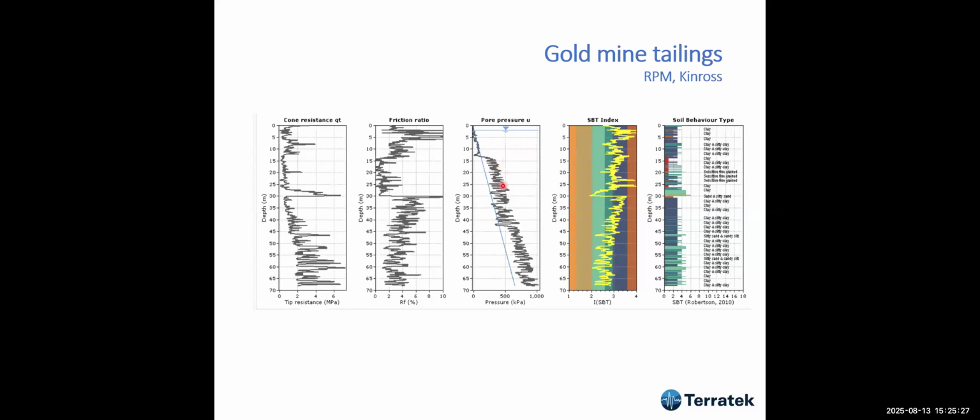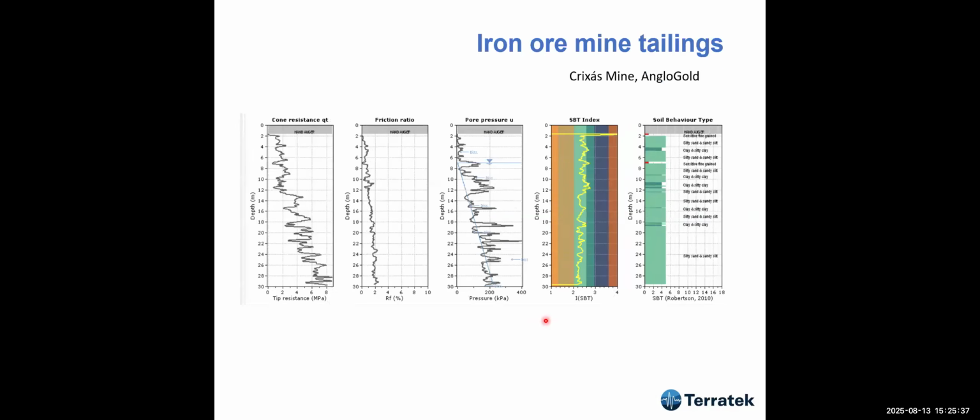They have a very high CV. So when you're changing the rods, the pore pressure reduces a lot. So very interesting. These are a kind of iron ore, more or less the same stuff. We have these many zigzags, not as much as the gold mine tailings. And here we did a lot of dissipation tests, which I'm going to address.